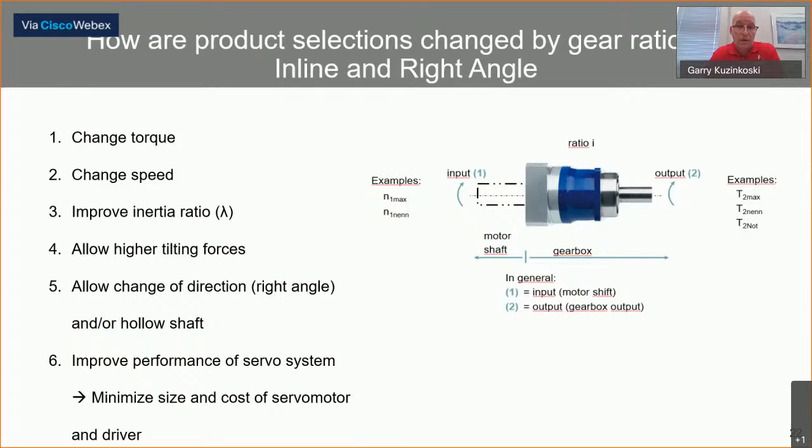But I'm also moving at a slower rate. That's item number 2. So my speed has gone down by 3/5 of the input. So instead of going, say, 300 RPMs, I may be going 200 RPMs. So it's going to offset the speed at which the output shaft actually moves.